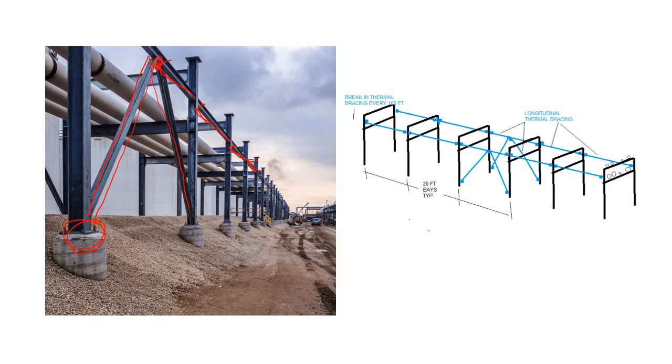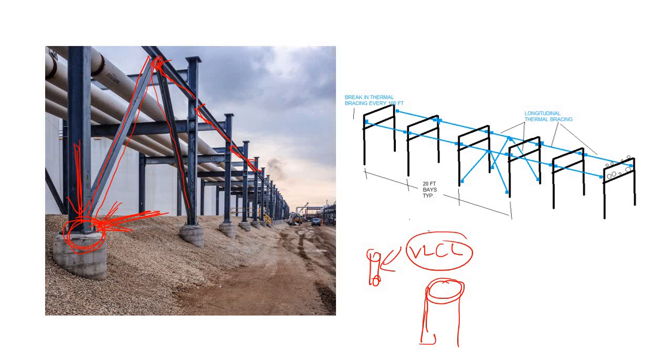Again here you can see there is a single pile. So you need to consider the horizontal force acting here as well as the vertical component. Normally the steel pile has sufficient vertical load carrying capacity, but you need to check the horizontal shear capacity because the piles are hollow in nature. The steel piles are hollow in nature. That is why you need to check the horizontal shear force carrying capacity of the pile.